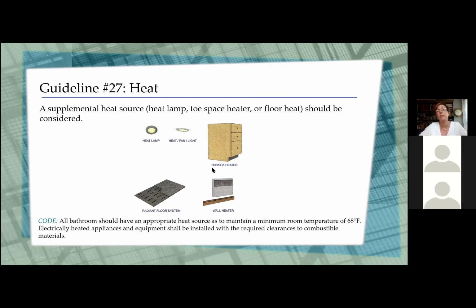And then there are wall heaters, which we've kind of moved away from over the years, but I know that in some parts of the country, they still do use those to help heat the spaces. Code just requires that bathrooms have an appropriate heat source, whether it's supplemental or otherwise, to maintain a temperature of about 68 degrees Fahrenheit. And then any electrically heated appliances just need to have the required clearances if there's any kind of combustible material in there. And they need to be rated